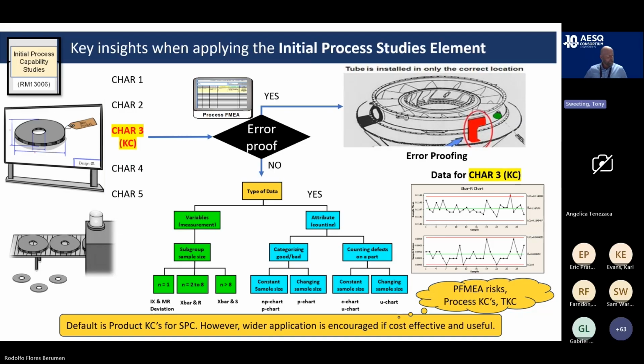Hi, thanks, Pete. Okay, so it looks very complicated, this stuff. But the main thing this one slide is trying to say is that straight away, you try and build quality into it. The best way of process control, the number one way, which was shown early on, is a good example of error proofing. We can't make something bad. So inspecting it would just confirm that I haven't made something bad. So in terms of error proofing, if you can go that way, go that way.